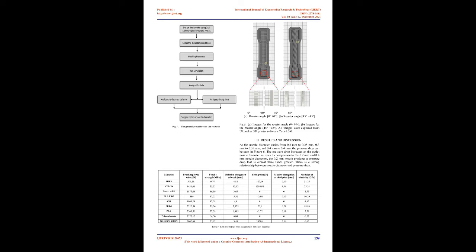FIA was used to investigate the flow behavior of PLA materials considering all boundary conditions. The flow of material inside the liquefier allowed us to observe the effect of varying nozzle diameter on pressure drop. Different nozzle diameters also affect printing time. A calculation and an experiment were conducted to analyze these issues and suggest the optimal nozzle diameter based on accuracy and printing time 12. The flow chart in Figure 2 illustrates the overall research method.